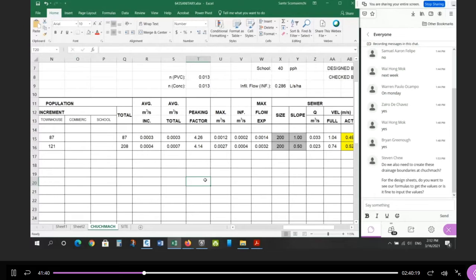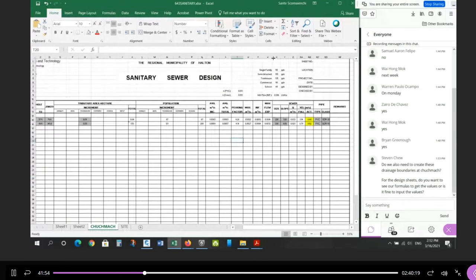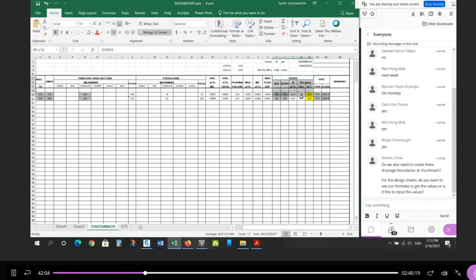All right. So there's a good way of checking whether you've programmed this correctly, right? Once you program this correctly, then you can cut and paste one cell into another and make sure that the reference is correct. Okay, so everything up to this point here, let me zoom out a little bit. Everything up to this point here, all of this stuff is calculating the expected flow. Everything on the other side is calculating an appropriate pipe size that can accommodate that flow.